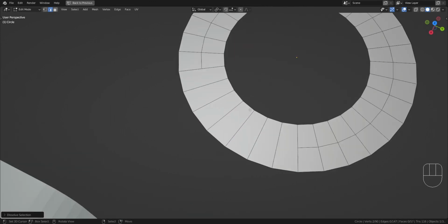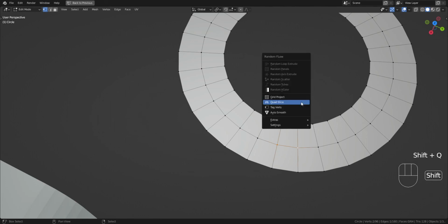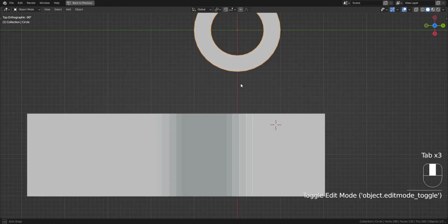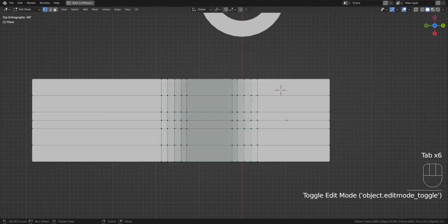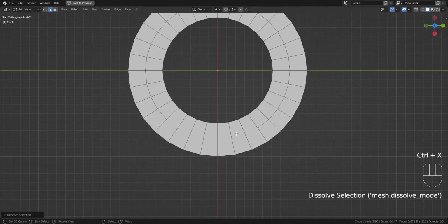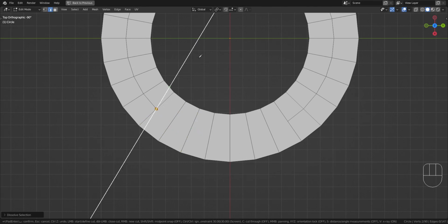Well, you can use vanilla tools in Blender. Ctrl R, J, select this, J. In order to supplement, or defeat, the limitation of the grid quad slice and grid project, use the inherent tools in Blender, like the knife. The knife in 3.0 is actually pretty good. K to activate the knife, A to activate snapping.